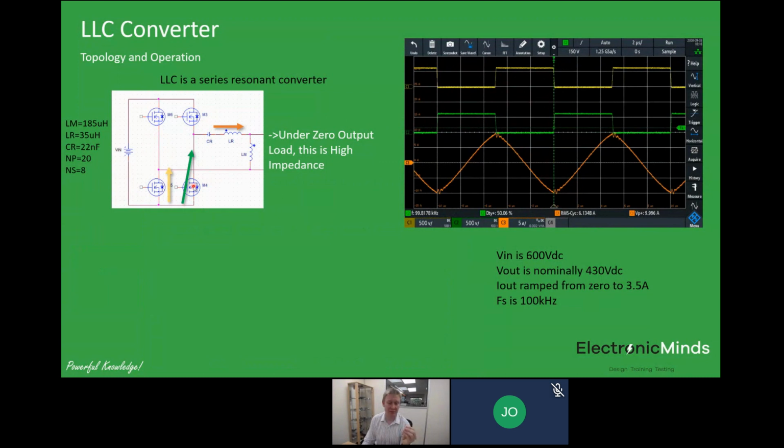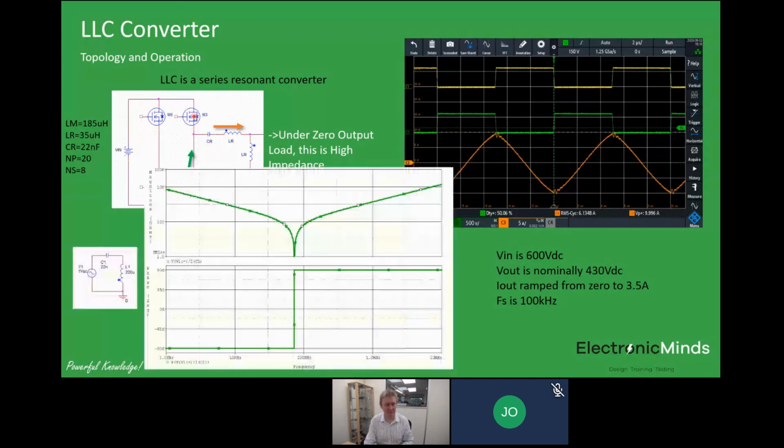So zero voltage switching is a great thing here. Now, that only happens when you've got inductive current flow in the system. If you had capacitive current flow, it would be a disaster. If you spend some time to work through all of the switching events, you can see that if you operate in the inductive region with sufficient current in your resonant tank, then you can always guarantee that these devices will zero voltage switch, as long as you leave enough dead time for the voltage to slew down. And that has a massive impact on efficiency, which I'll show you in a slide in a minute.